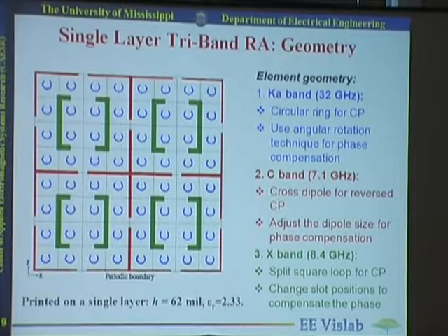People, when they design reflectarrays, design them for one frequency. If they need a second frequency to work on, they add another layer. A third frequency, they put a third layer. That's very costly and very cumbersome. Here we have designed a one-layer reflectarray supporting three frequencies.